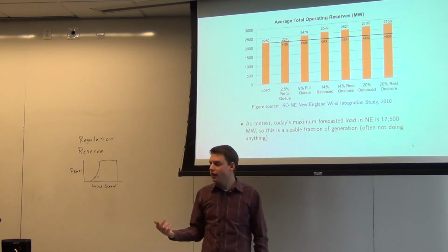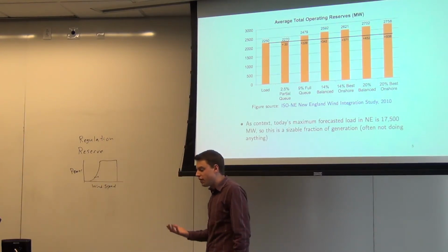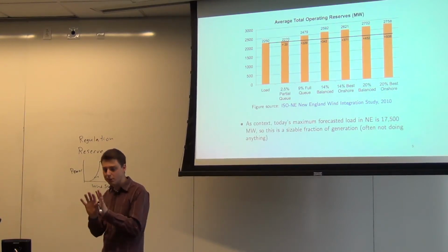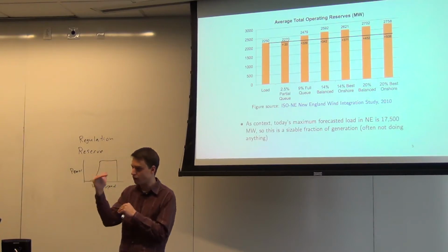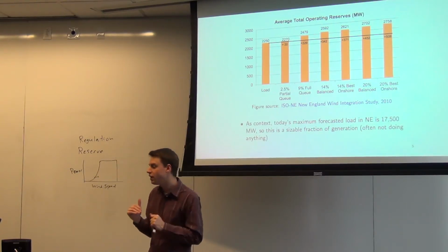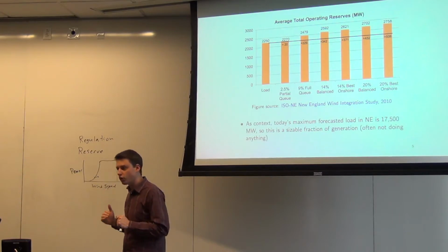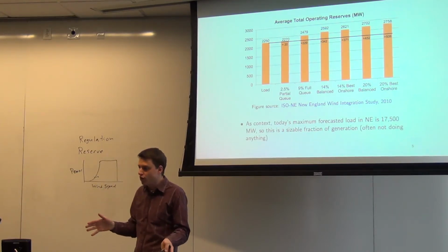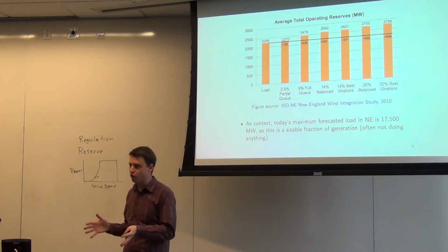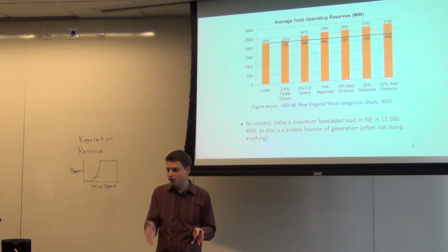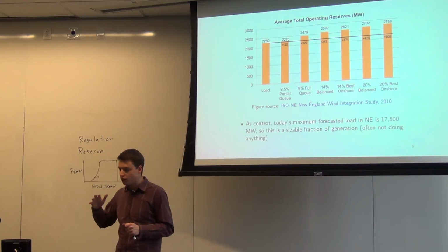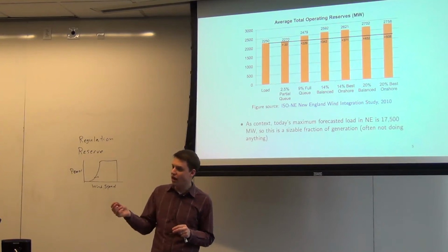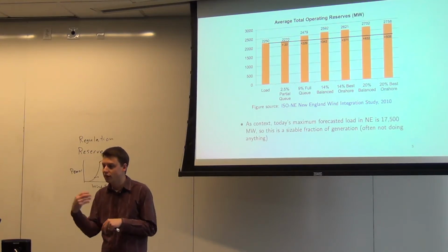Reserve is more something like, well, we know that the total power consumed, so ignoring frequency, just thinking about total power mismatch between what's being used and what's being generated, we know we're not going to be quite right in our forecast. So on the level of 5 minutes or so, we're going to have some error. And so this we also want to be able to account for. But this actually happens right now still also, right? So certainly even if you schedule big generators, which you can schedule, you're not going to be exactly right in your predictions.